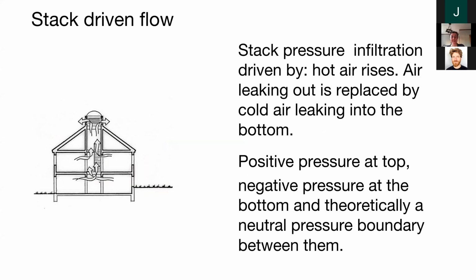You might also have stack-driven flow leading to infiltration. That happens because hot air rises, and so then cold air comes in, leaks in from the bottom. So that also leads to these pressure differences that can bring a lot of air infiltration in and out of the building.